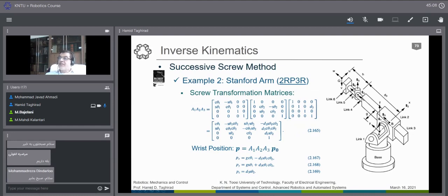As I mentioned, the P is not directly given. Usually in inverse kinematics, Q is given, this point. But the Q and P have only an H difference in the Z direction. So from one, we can get the other quite easily by a simple manipulation. So we go with the P. We assume that Px, Py, Pz is found from Qx, Qy, Qz, and this H parameter, this H length of the end effector. And we use this relation here.